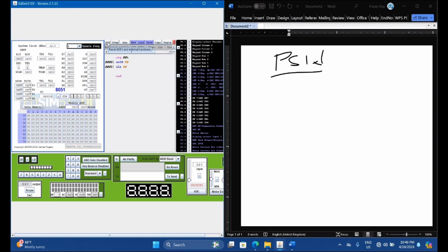You either set it or you don't set it, or either select it or you don't select it. So that's the next one. The RS1 and RS0, like I said, are used to indicate the register banks. They are the register bank selectors. We can't go into register banks now because it's under memory organization. But basically, we have about 4 banks.